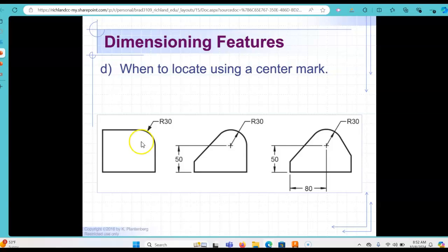We know as technicians, readers and engineers that there's a tangency point on that radius up here and a tangency point of the radius there. When we follow it back, the center of the arc is at those tangency points, and we would know exactly where that is just because we're aware of the geometry on the print.